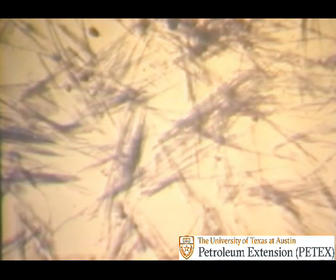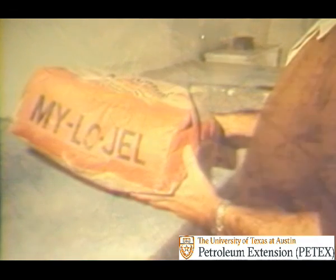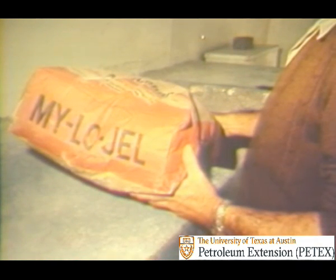A photo through a microscope shows attapulgite's needle-like shape. Because of its shape, attapulgite doesn't provide much filtration control. There are no nice flat particles to stack up on the wall of the hole. So in attapulgite muds, fluid loss is controlled by adding starch, as is being done here, or cellulose to the mud system.